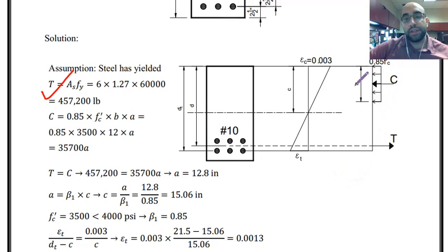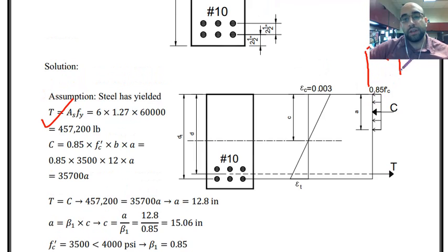Then we have the compressive region. The compressive stress is distributed over here. Total compression force that I have is a stress multiplied by area that we have under this stress, that is a, depth of it, multiplied by b, width of it, which is width of the section. As you remember, if I want to look at the 3D view, it looks like this, and then this is applied over here in the compressive region.